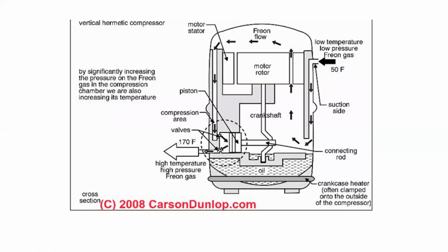Hermetically sealed motor compressors have a section in section 28 that discusses their operation and sizing requirements. What's important to realize is that this type of motor is mechanically connected by a crankshaft to the piston that is creating the compression of the refrigerant itself. The type of refrigerant that is utilized actually flows around the motor itself, and there is a small quantity of oil in the bottom to ensure that the connecting rod is adequately lubricated.